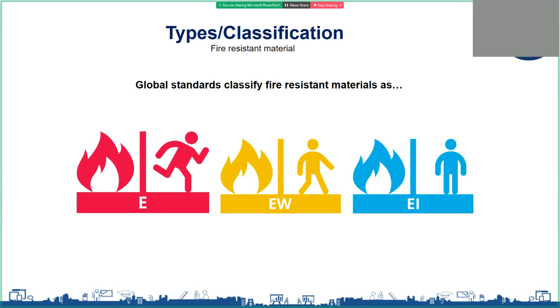But when it comes to fire control, stopping flames and smoke might be just one part, because whenever an integrity-rated material is exposed to fire, it starts to heat up. Beyond a certain point, it will be hot enough to emit enough radiation that the heat of the fire is transferred to the other side indirectly.